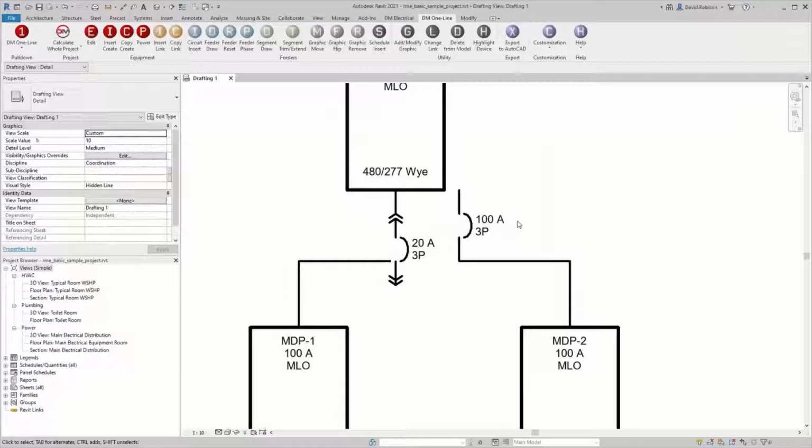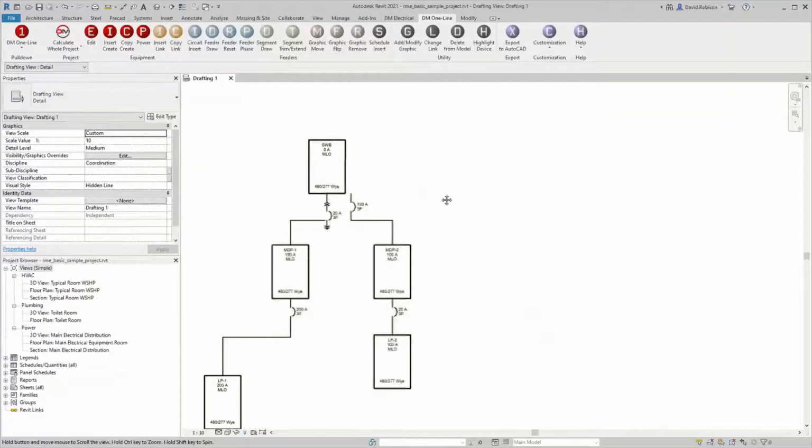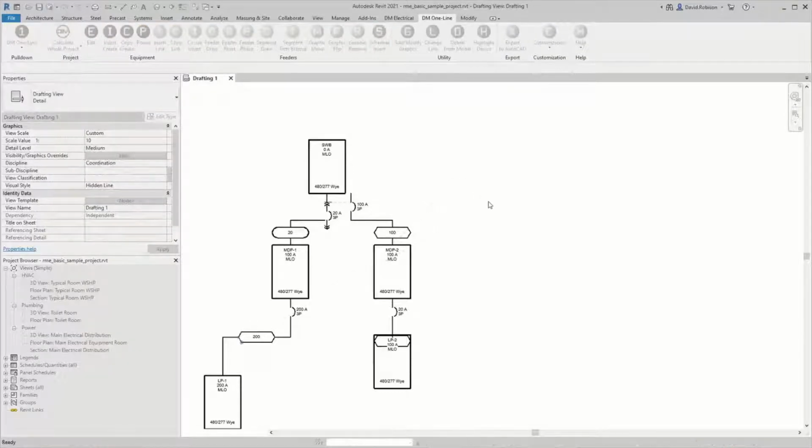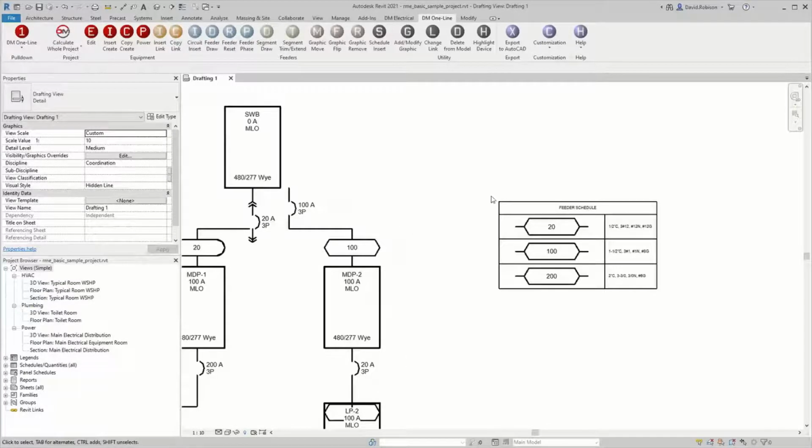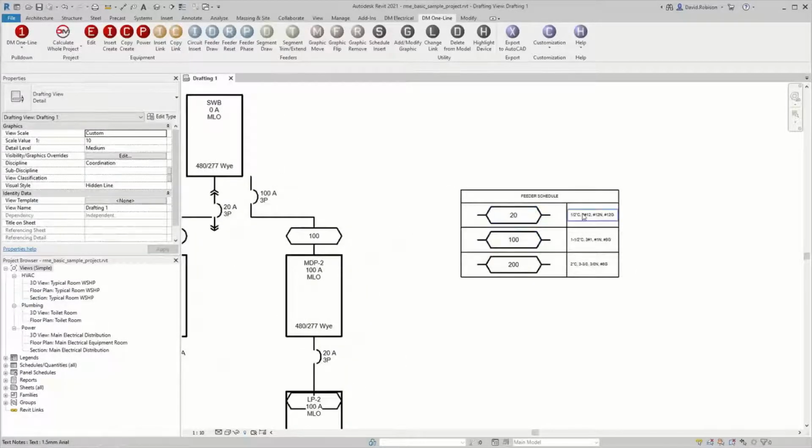which didn't actually make it into beta 8, but beta 9, which I'm going to release tomorrow morning, has a feeder ID schedule. So the schedule insert, which is not in beta 8, it will be in beta 9, again, coming out tomorrow. You give it a point, and it will draw a feeder schedule for you. So basically, it's going to show you the graphic and then what the corresponding wire callout is for that graphic.